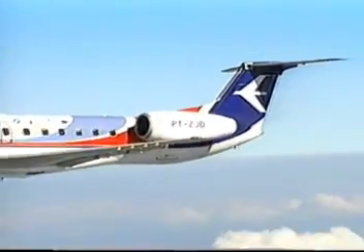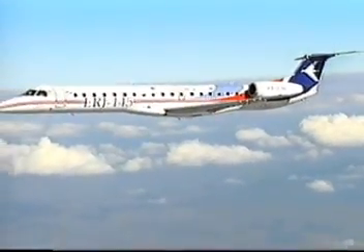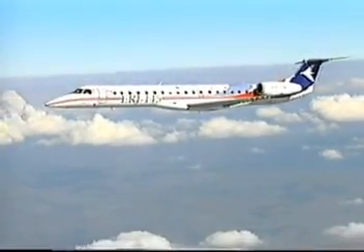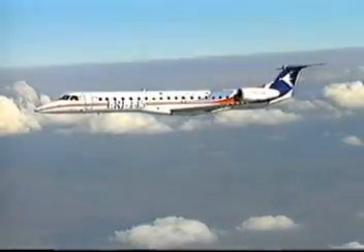And you can't profit from this spectacular effect on the turbofan aircraft. No lift bonus is available because the jet efflux is discharged clear aft and does not pass over the wings. Moreover, just as the propeller produces lift, accelerating rapidly under some flight conditions, it can be used to produce drag. When throttles are set to idle, the propeller produces drag, that is, negative thrust. The higher the RPM, the higher the drag.